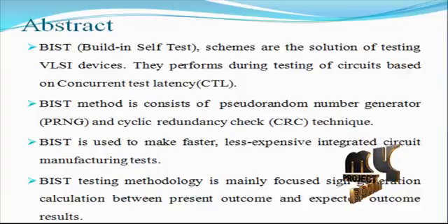Although over the next years the primary objective of manufacturing test will remain essentially the same, to ensure reliable and high quality semiconductor product conditions, the test solution may consequently undergo significant evolution. This paper describes a low power programmable generator capable of producing pseudo random test patterns with desired toggling level and enhanced fault coverage gradient compared with the best to date built-in self-test based pseudo random pattern test pattern generators.